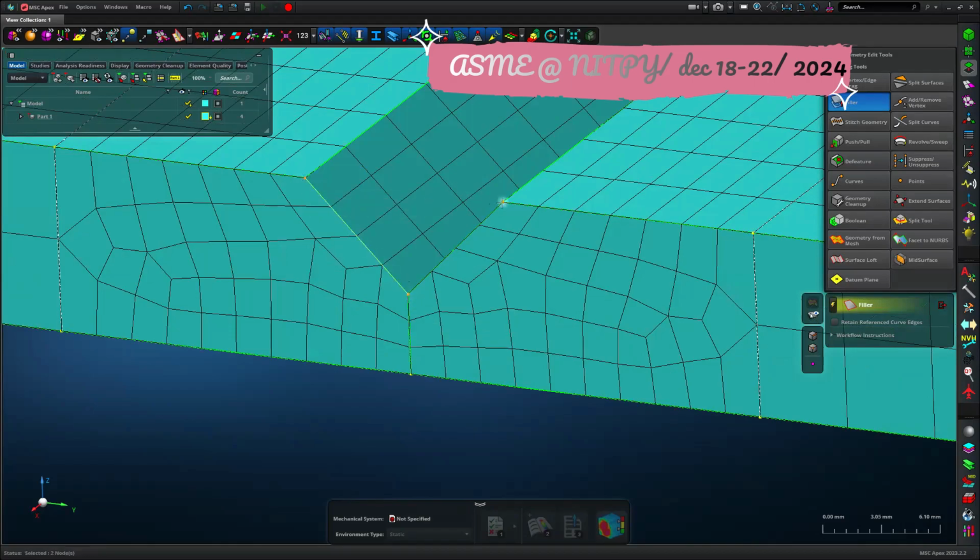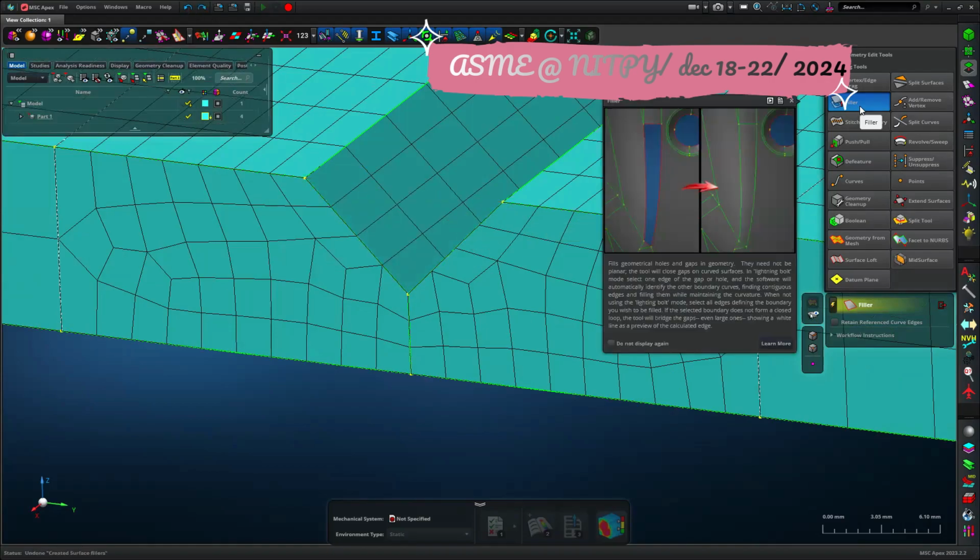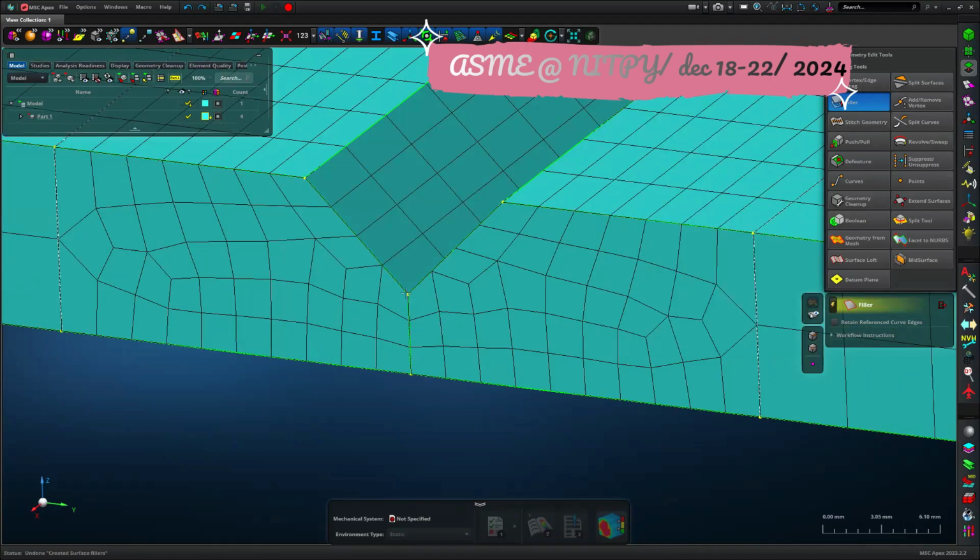Are you able to find the fillet option? Yes, sir. So there, in the fillet option, you click on it and you can just zoom to this triangular location, where we have created the groove. There you use your shift button. Press the shift button, then click the 3 points there.